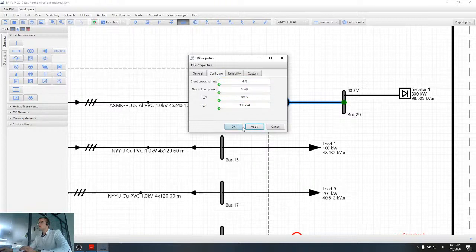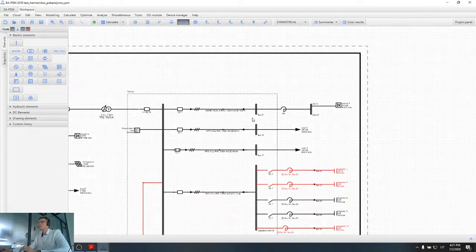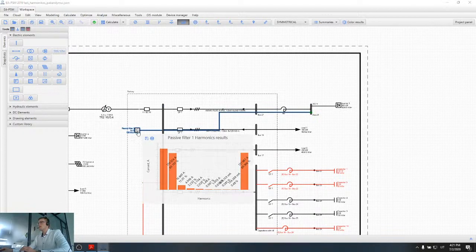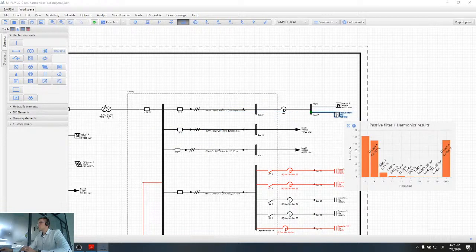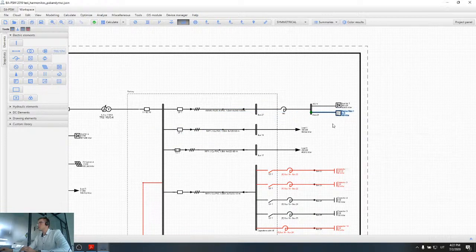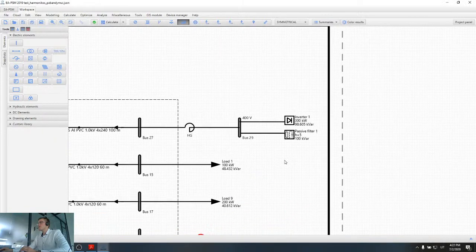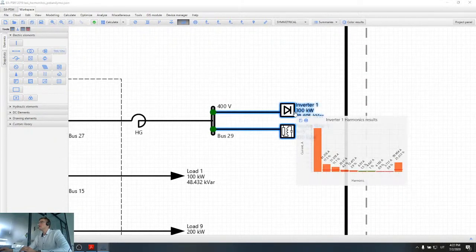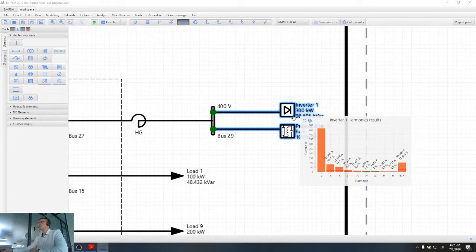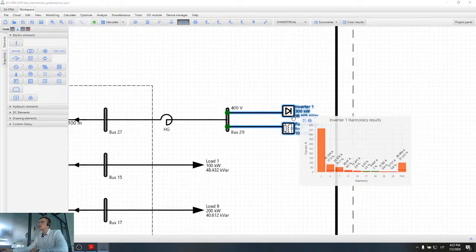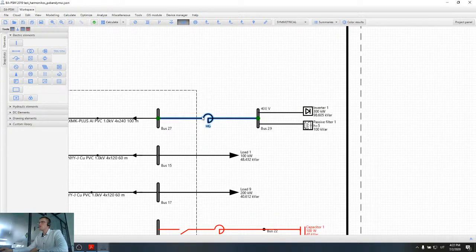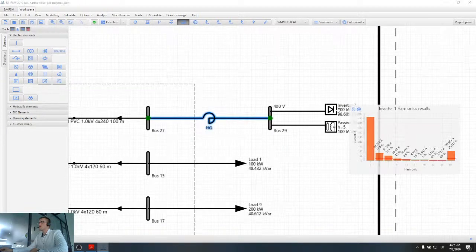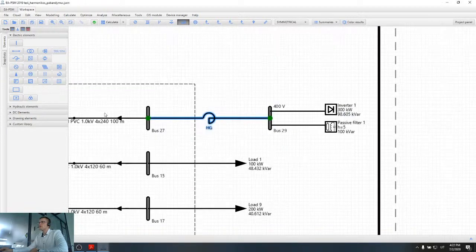3 kilowatt. These are the losses of the harmonic gate, and when I have the harmonic gate connected, I can then reconnect my filter here to the inverter connection point. So here I now have the tuned harmonic filter for single nonlinear load harmonics reduction, and I have this harmonic gate which won't allow harmonics to enter into the network.